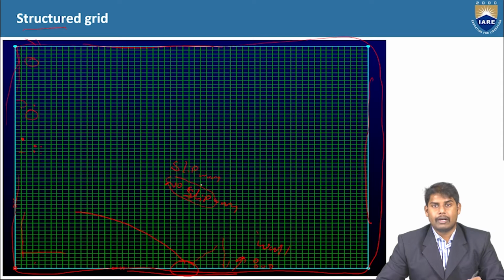The first fluid particle which is coming and hitting the wall surface will stick and it will not move. This is called the no slip condition. And a slip wall is nothing but a wall where these fluid particles will not stick, so they will move actually. So this kind of condition is nothing but a no slip condition.